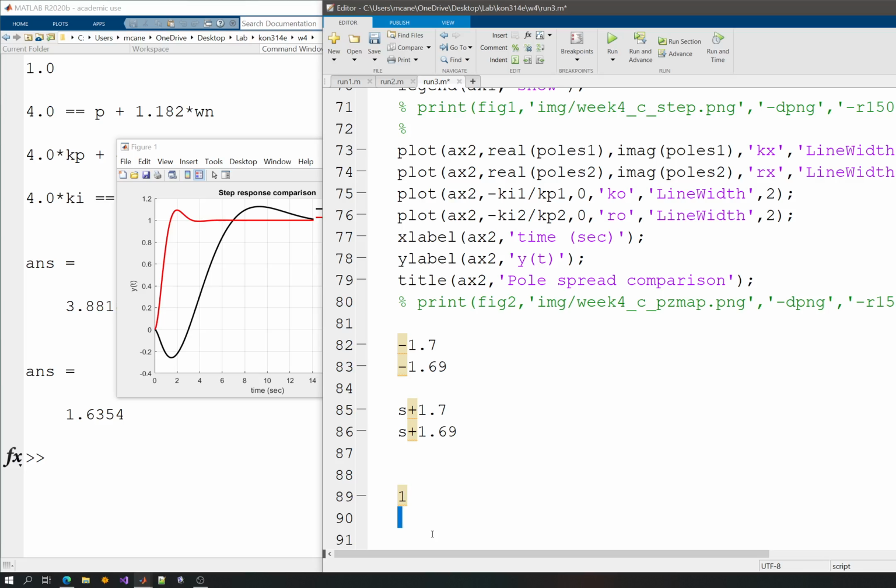Your feedback structure will compensate for that, because you have a feedback structure, you have error, and your controller, if you have a stable controller or stable control system, closed loop, then the error should tend to zero at steady state. So if there's something happen, transients happen, then you will tend to zero for the error. And if that's the case, then your reference tracking will be successful.